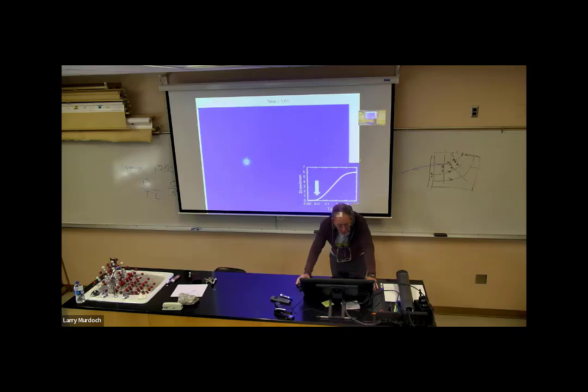Now we pump a little bit more, and you can see this grid. You can see these little squares. This is from the grid that you saw when you did the models for the flow nets. The hydraulic head has now dropped in this area and the drawdown has increased. This is 0.01, and in the time series, it's right here. You can see now we have a little bit of drawdown. We're measuring it right there, so you can see it's a little bit of light blue.